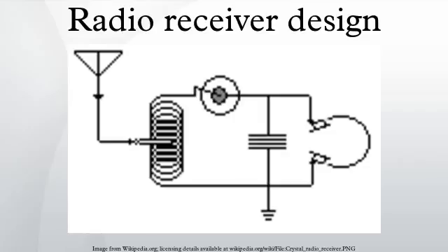For receiving CW, the local oscillator is tuned to a frequency slightly different from that of the transmitter in order to turn the received signal into an audible beep. Advantages: simpler than a superheterodyne receiver. Disadvantages: poor rejection of strong signals at adjacent frequencies compared to a superheterodyne receiver, and increased noise or interference when receiving a SSB signal since there is no selectivity against the undesired sideband.